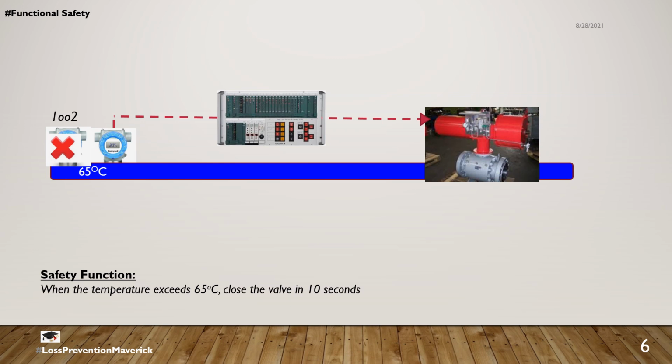All this will come later when we talk about hardware concepts, but here the voting principle was available, and therefore though this particular error happened in one of the transmitters, still the safety function was executed, and that particular state of SIF is called an intermediate state, and that is the fourth state.